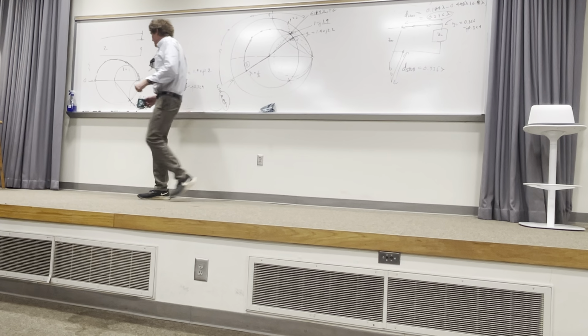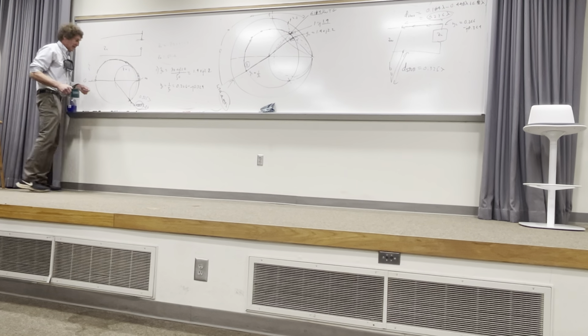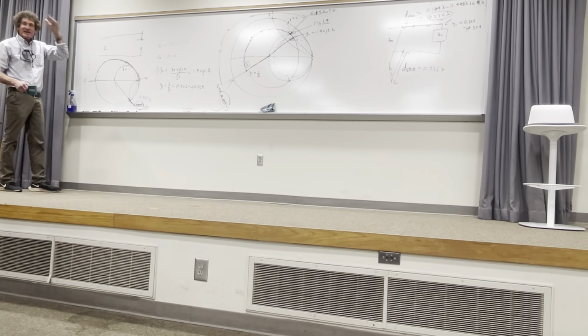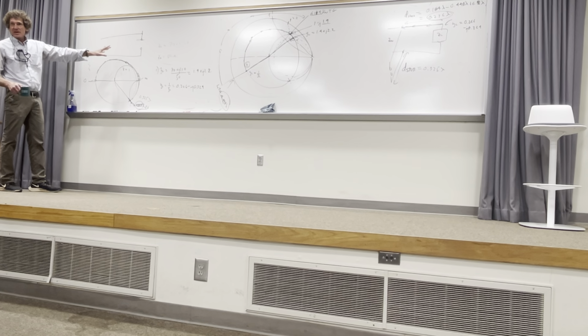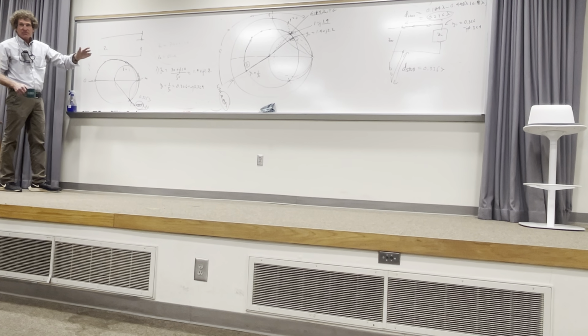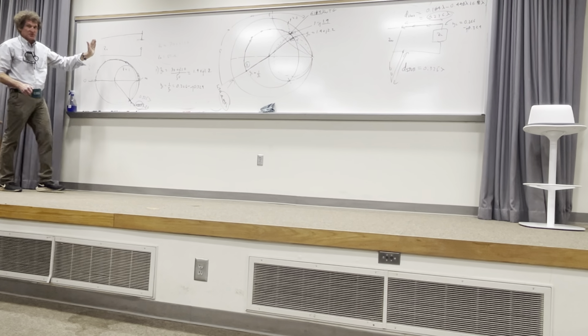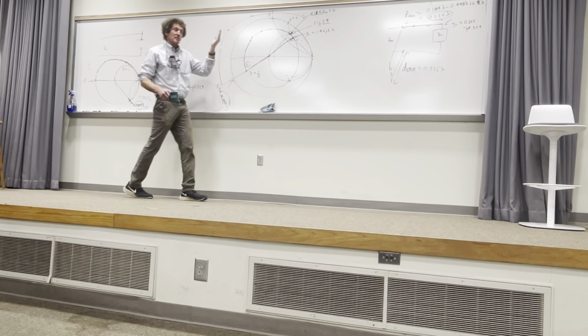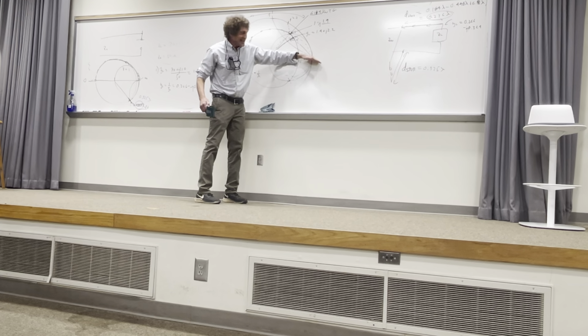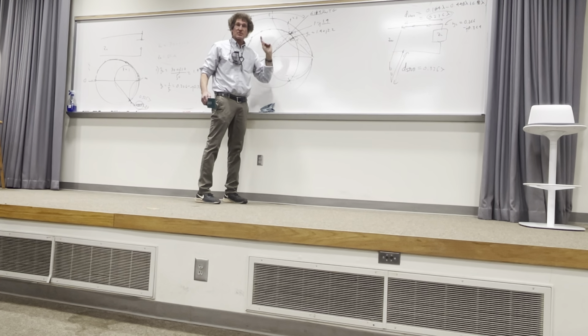I could come up with about 3 or 4 other things, but the constraints are things that you think about, and think about the fundamental thing you have to deal with. If they want the minimal length of the stub, then you always got to figure, if it's a short circuit stub in parallel, the values of Y are negative J. That means we want our attachment point to be 1 plus J, whatever that imaginary part is.